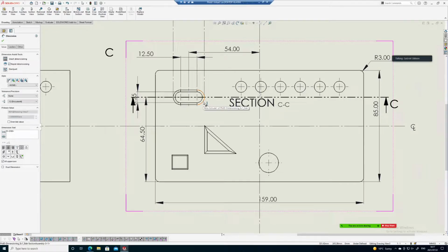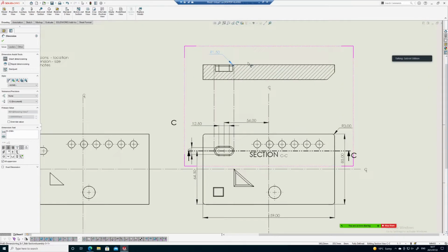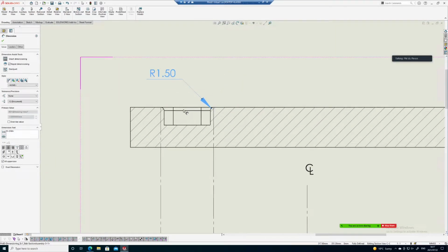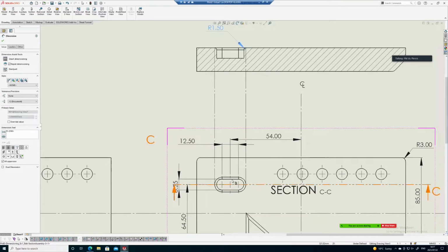Could it be very convenient though for actually manufacturing it? If you just had the top view and it could say, you need to countersink this to this depth with this angle, and then you need to add a radius to these? Well, once again, all the features that you need to dimension regarding the depth are in this view, not in this view. Yes, okay, fair enough. You could actually put in a note here. You could put in slots. Yeah, you absolutely could.